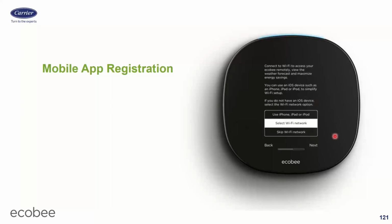The other choice you could do is if you don't know the Wi-Fi password or the homeowner doesn't know it, you can use the iPhone section, and if there's already an iPhone or other iDevice connected to that homeowner's Wi-Fi, the iPhone can push the password into the thermostat without you ever seeing or knowing the password. Now, in order for that to happen, the customer has to have an iPhone, and the iPhone has to be on the same Wi-Fi network as the thermostat. It can't be your iPhone as the installer because you're not on their Wi-Fi. It has to be their iPhone, right, or their kid's iPad or whatever.